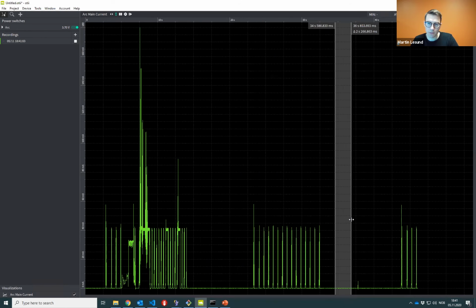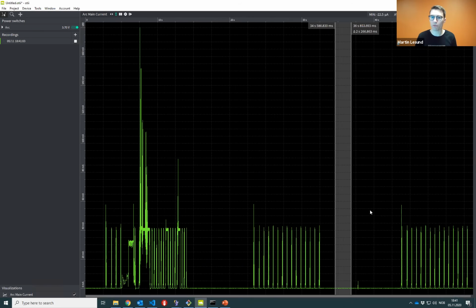And in between here, we can see that the average current is 38. That's quite high. Why is that? That's because the SIM card is not turned off. The SIM card is not in shutdown mode. It's called idle mode. So we can see that the SIM card is actually using a lot more current than the nRF9160 SiP itself.